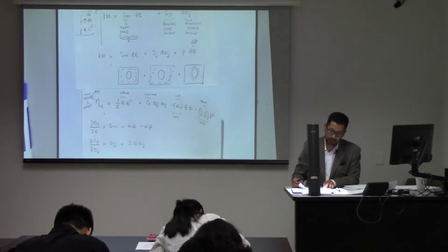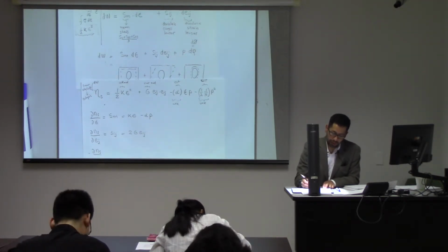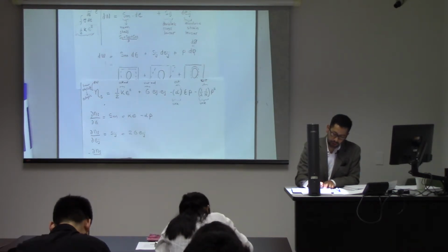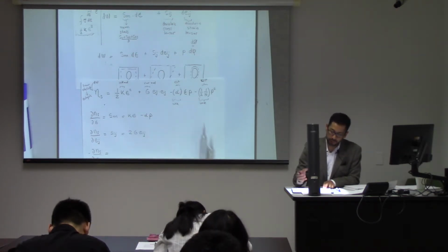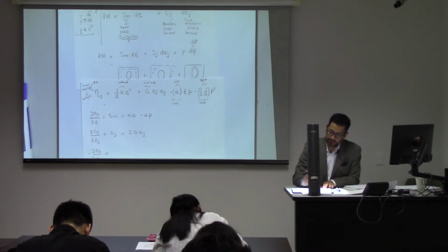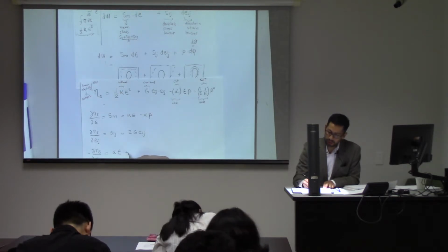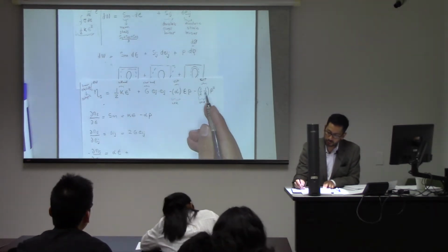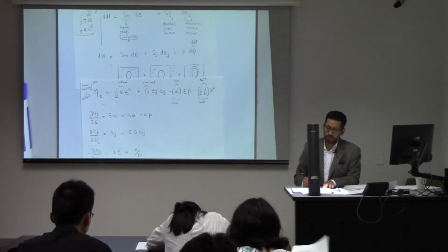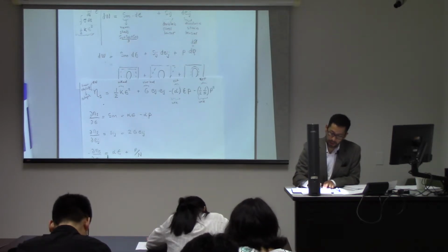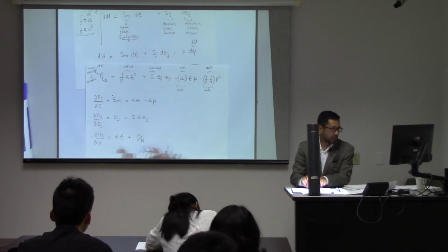And if I take the negative of the derivative of the free energy of the porous solid with respect to pressure now, no pressure here, no pressure there, I have a pressure here, and it is negative, so this is going to be alpha times the volumetric strain plus 2p, and that cancels out, p over n. And I forgot to write this over here, but let me move this equation a little bit to the right, okay?